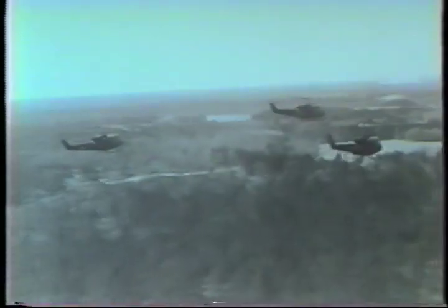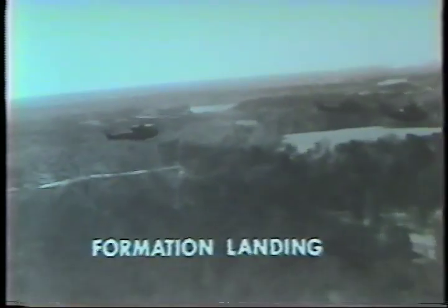A formation landing is a landing during which all elements of a formation touch down at the same time while maintaining their relative position within the formation. It is the responsibility of the formation leader to ensure that sufficient obstacle clearance and landing space is provided for all aircraft in the formation. The lead element must maintain straight and level flight until the correct approach angle is intercepted, avoiding an excessive steep or shallow approach angle.